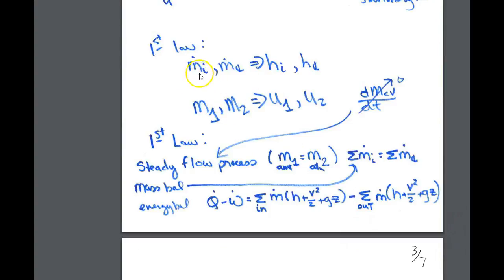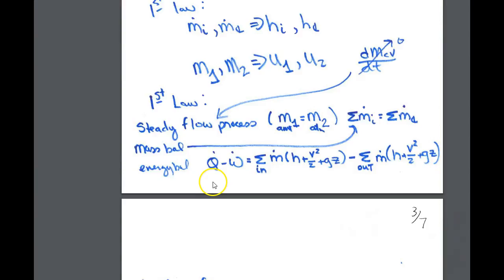So just to break it down, if we have mass flow rates, m_i dot, those are the mass flow rates coming in, m_e dot, the mass flow rates coming out, we'll generally see the energy term associated with those streams as being H for H in and H out, whereas the masses within the control volumes at time 1 and time 2, which are subscripted 1 and 2, are more commonly U values or internal energy values.